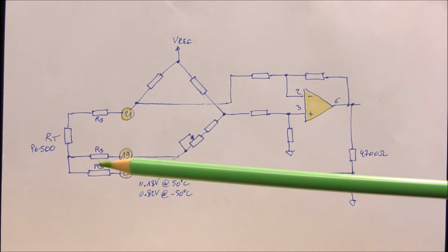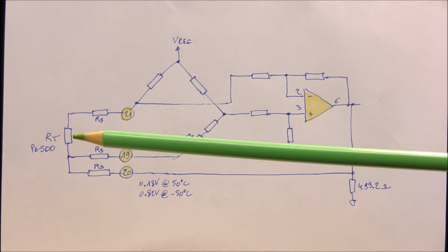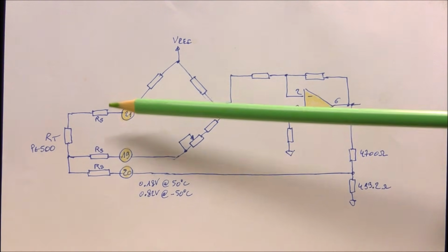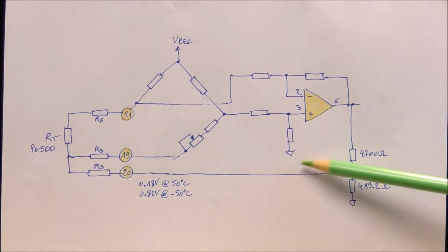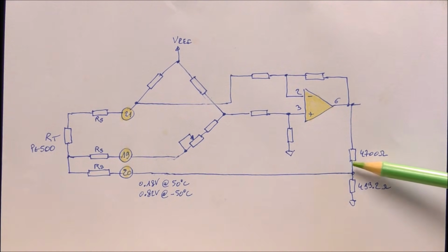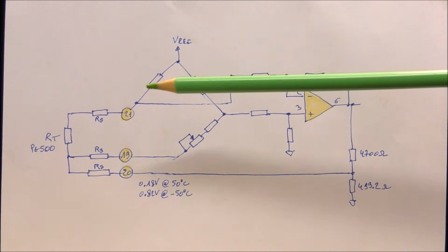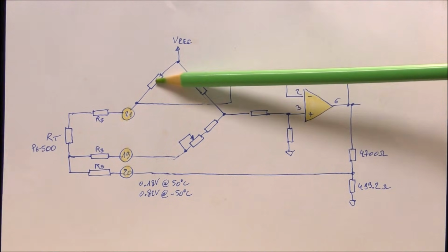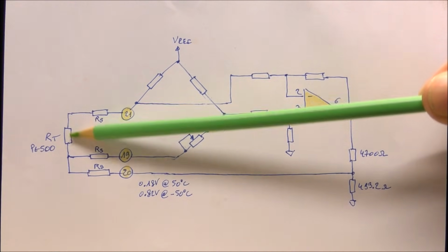These 3 resistors RS modelize the cable from the indicator to the total air temperature probe. These 3 resistors are identical. The return point is here. It is connected to this voltage divider. We will see in one moment why we have this voltage divider. So you can see that the left leg is here, this resistor, this parasitic resistance, and the platinum sensor.